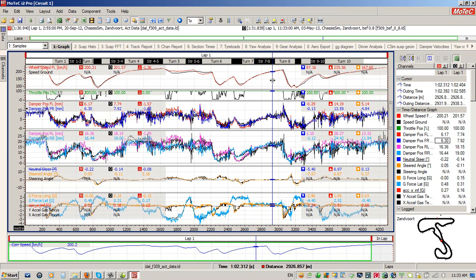Now, at this point, you're ready to run the auto grip. If I was to run this in complete fire-and-forget mode, I would automatically have gone curvature file, bump profile, altitude, road camber file, auto grip scale, then done the auto grip scaling factor. However, I've done it this way so you can actually see what's going on, because just remember, our goal here is to create as good a representative environment as possible of the race car. So let's have a quick look.